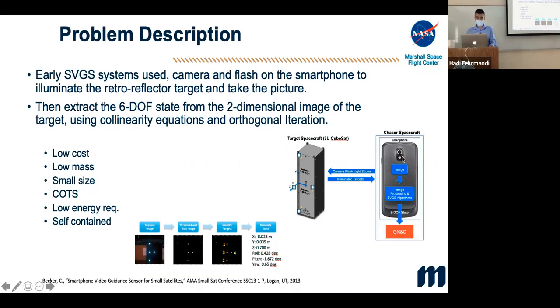The reason for a smartphone is that a very low-cost Android smartphone camera can take an image and filter it, as you see here in the picture. That can be filtered and associated with the data. And if we know the original size of the target, it's possible, based on the geometric relationship, to obtain the camera's point of view: XYZ and roll, yaw, pitch.